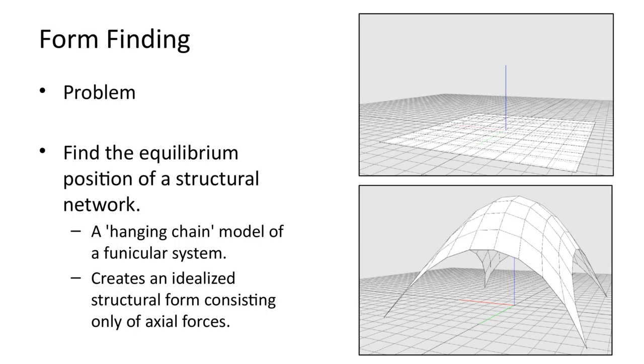In our example, the problem is a form-finding task. The aim is to find an efficient structural form, called a catenary structure. A catenary is the idealized form generated by a hanging chain structure. The chains are attached at key points, and the structure is allowed to hang under its own weight. This will create a U-shaped type of structure. If this structure is inverted, it creates arches or domes that can be structurally efficient.